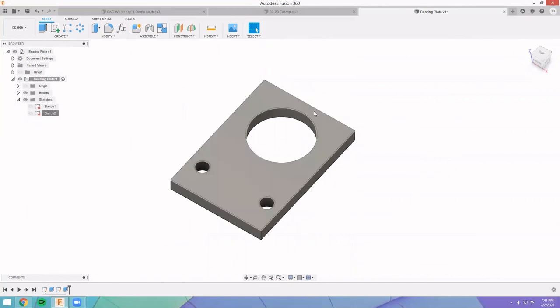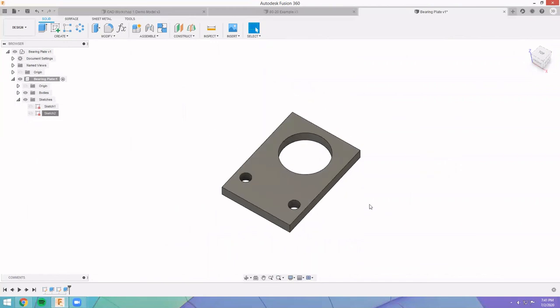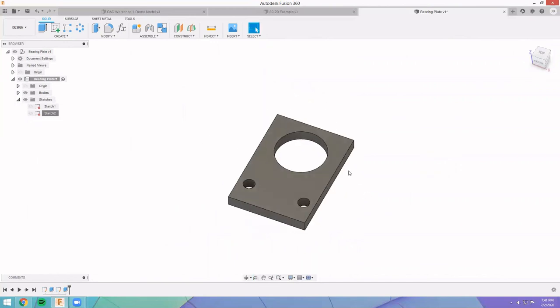So this is another way that parametric modeling will come in handy. A lot of the times on the robot we'll say, this was great, but we needed it to be an inch further, or like compression on the ball. And if that was the case, you could just go back and change that variable we made, the plate height, to be an inch higher, and change that line to be an inch higher, and you'd be done, instead of having to redraw the entire thing with this an inch higher.